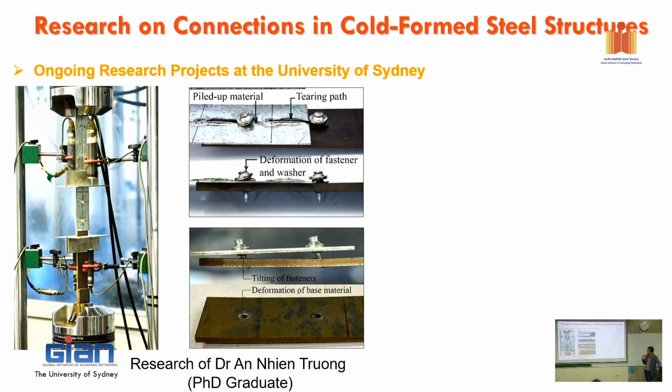So even with PAP as well, let me explain a little bit of the behavior. There's a failure mode that is very interesting because the bottom is thick and the PAP is going this way, and you pull it down, and if this PAP is strong enough, it just tilts a little bit and just pulls out. It's pulling now. So that failure mode we call pull out by shear.